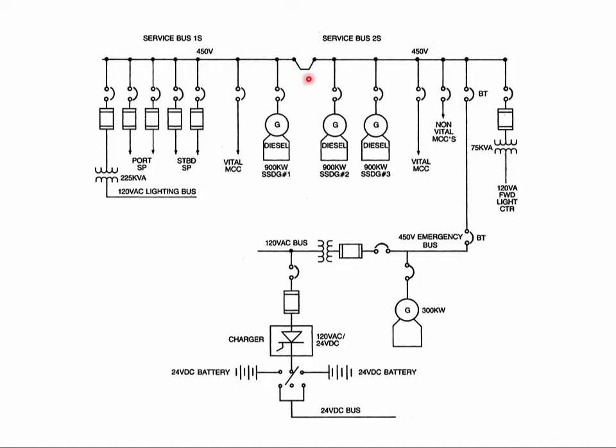In this case up here, this would only be used in an emergency. But if you had a major emergency, where a part of the board, say, was destroyed, so let's say there was an electrical fire on this part of the board, you would have to shut down all power to the ship, including the emergency generator. Everything would have to be dead. You can get in behind, and mechanically, and I mean you'd go in there with a socket wrench, unbolt part of the bus to separate this board. And then you have these 2 generators that you could bring online to power up this side.